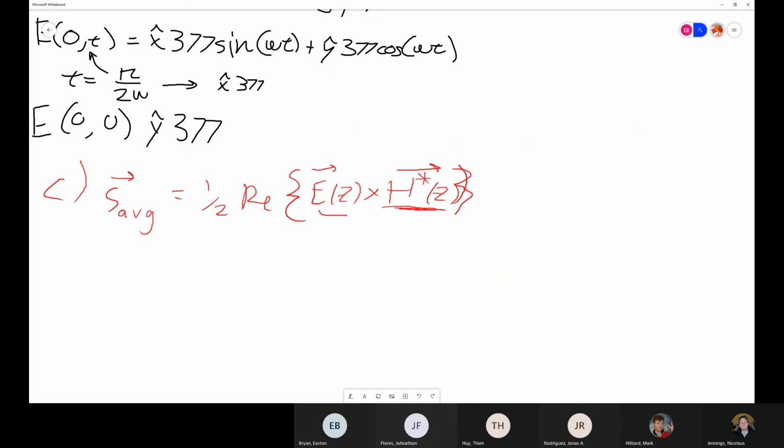please? Yeah, it's kind of like an inverse of a fraction or something like that. Okay. Yeah, there's also a thing on the calculator for conjugate. But basically, you just flip the sign on the angle in the phasor form, and you'll be good to go.